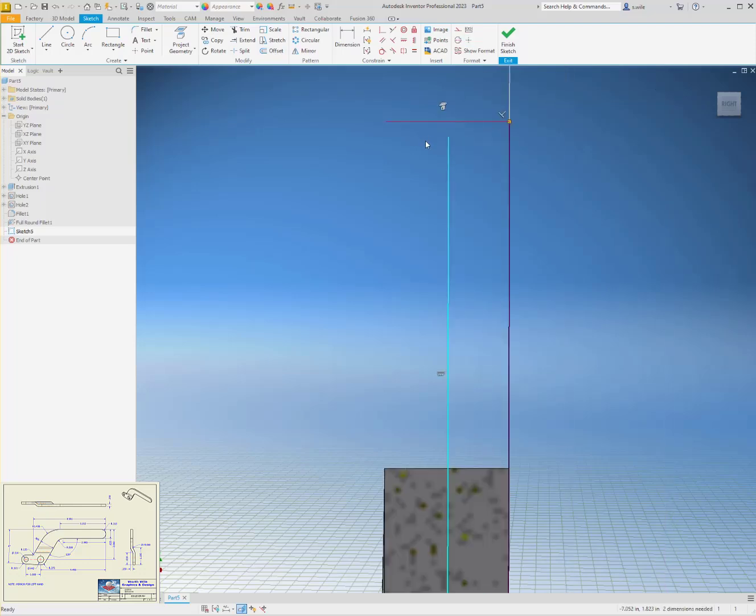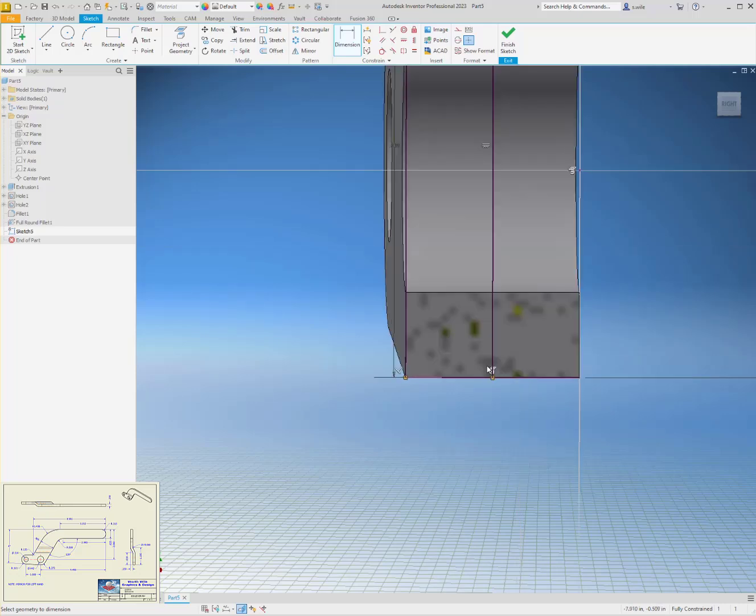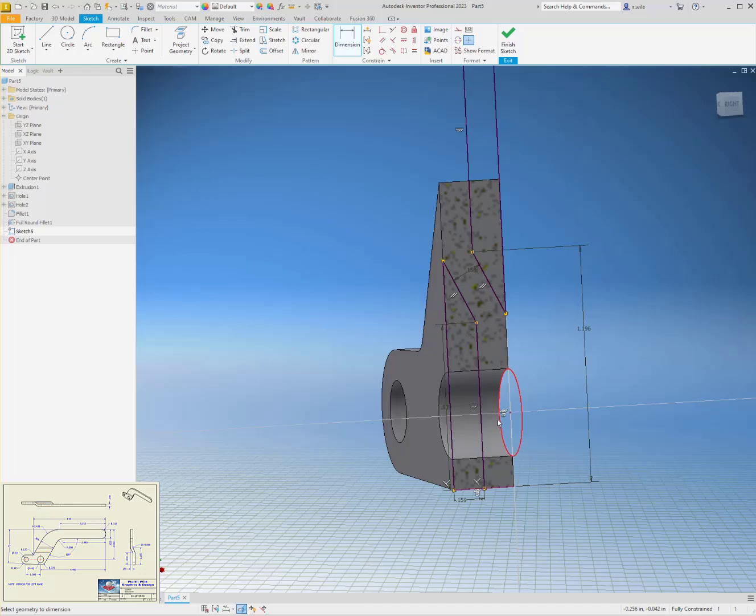All right, so we can move him, and then we'll put him back on, not in the center. And this will be the thickness of the cutout, 0.159, a little bit over center. And then this, gonna move it over here, then back down, not in the center. This is a cutout, and the cutouts are 0.159, so a little bit more than the thickness. And then this would be the thickness. So now we should have a consistent thickness down through here.